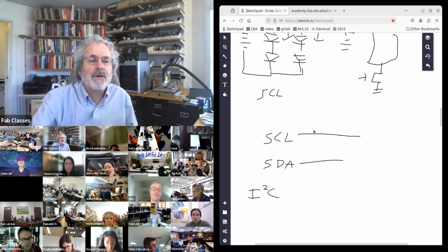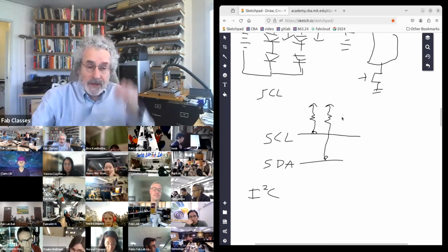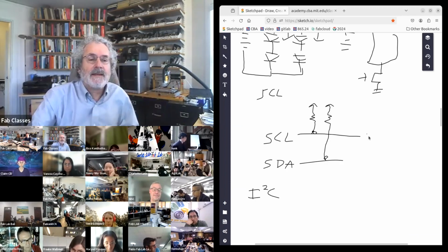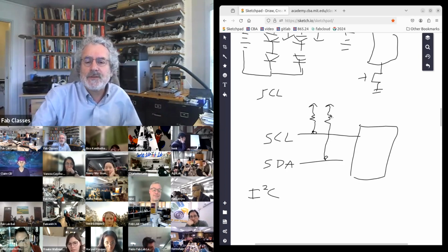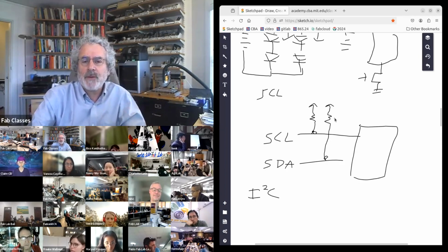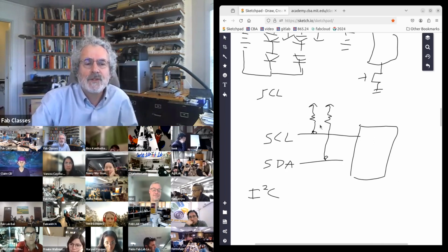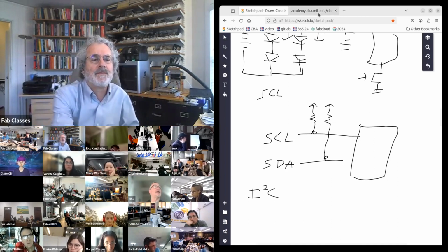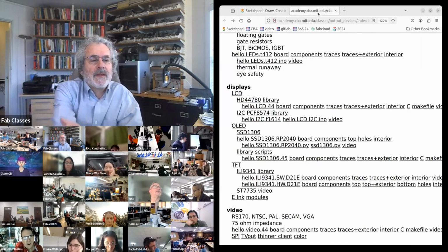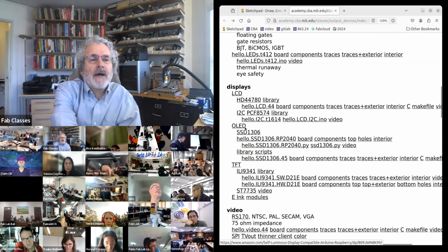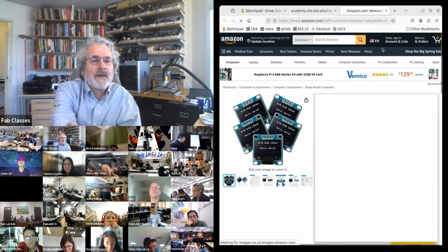They need pull-up resistors somewhere between 1 and 10K. And typically, those resistors are on breakout boards if you buy a breakout board. If you make your own circuit, you need to put the resistors in. So in this example, I'm using the module that has the pull-up resistors.